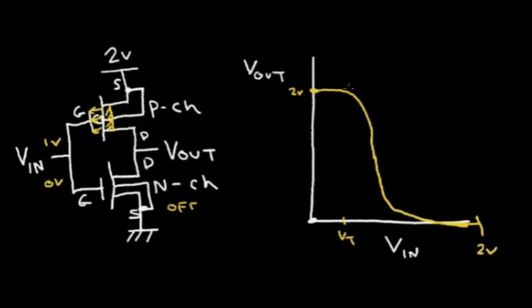And the significant thing is that in this part of the curve we're drawing essentially no power dissipation, and in this part of the curve there's no power dissipation because both transistors are off. Now when both transistors are on for a brief time, when things are switching, we get a current. If I plot the drain current, I'll get a spike of current, something like this, where this is the I drain, or the current flowing in this branch, I drain.